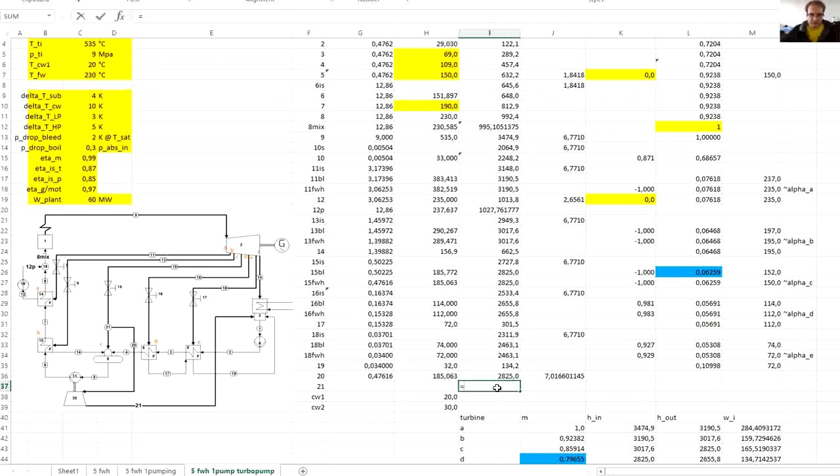And the enthalpy at point 21 is enthalpy at point 20 minus the enthalpy difference, 20 minus the function of enthalpy at the pressure after expansion and the entropy before the expansion, and this difference is multiplied by the isentropic efficiency of the turbine.